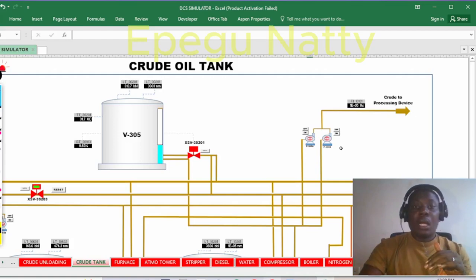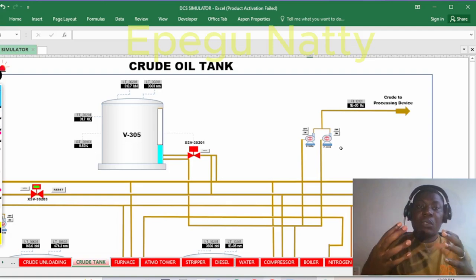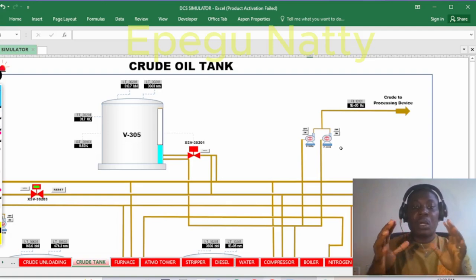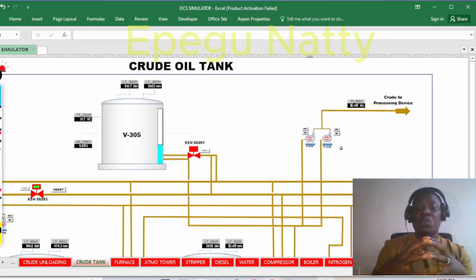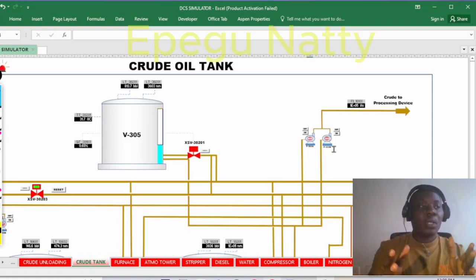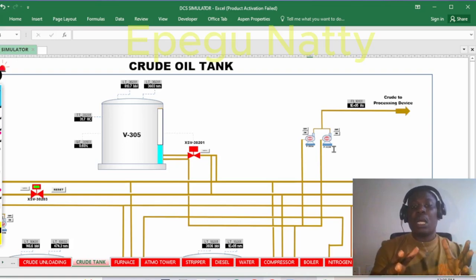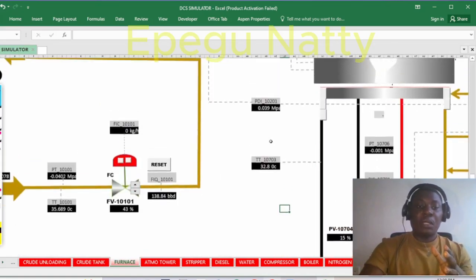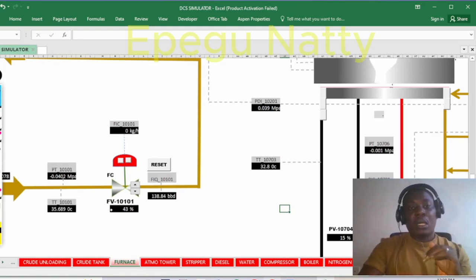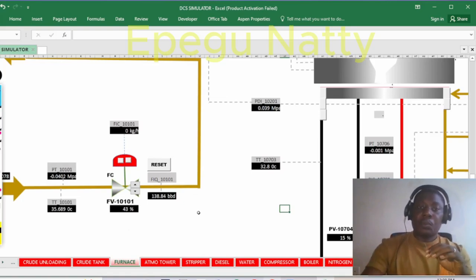But then the question now is, there are some limitations to the knowledge that the control room operator is actually getting, right? When it comes to the pump performance, for example, we only know that we put on the pump and then we use the control valves to actually control the flow of what is going to our system. All right, we try to balance the level, and that is exactly the idea that is being taught to control operators, to balance these levels to ensure that the temperature and pressure don't exceed the maximum range. These are what we do. But then we need to go deeper.